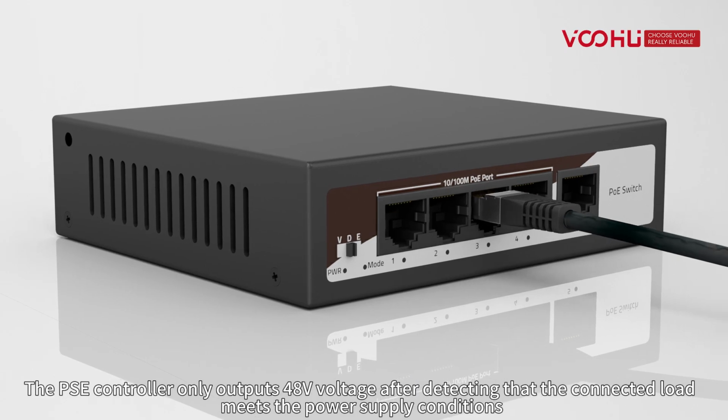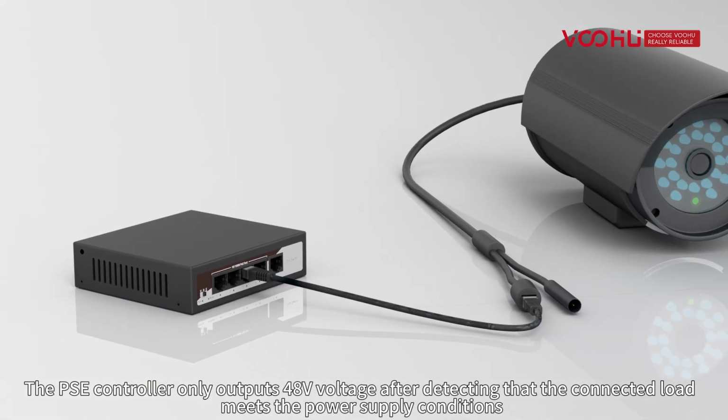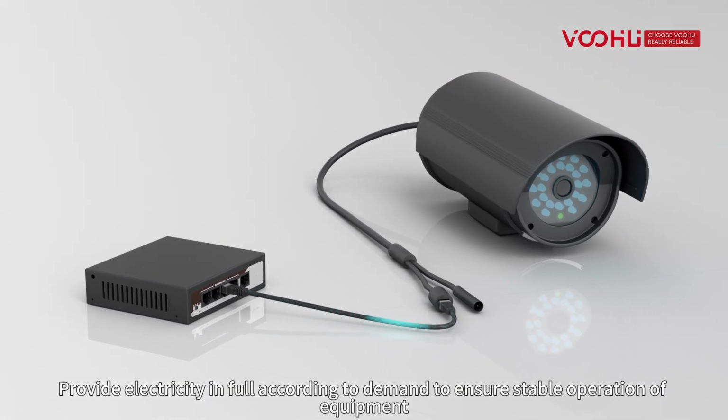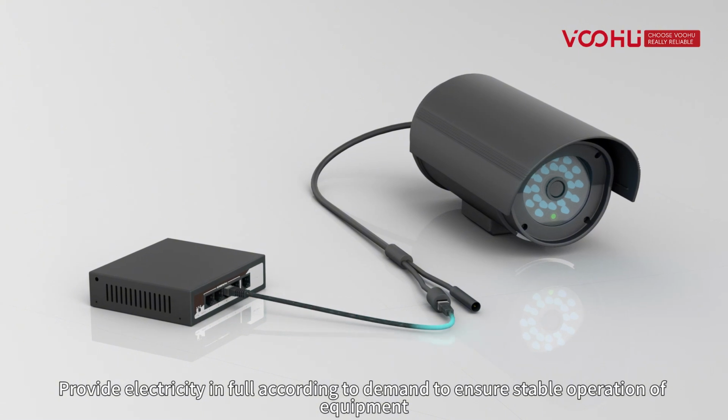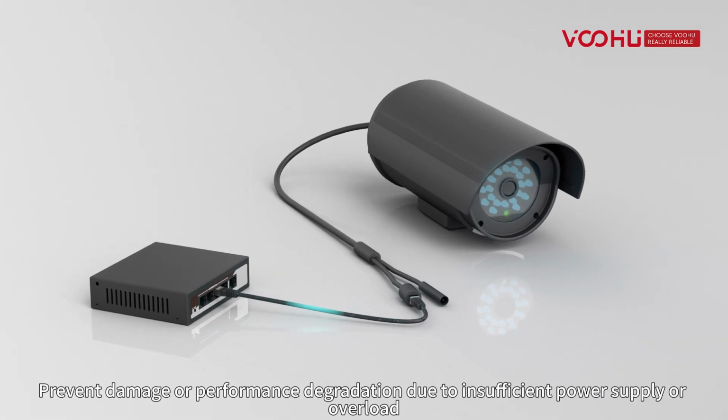The PSE controller only outputs 48 volts after detecting that the connected load meets the power supply conditions. It provides electricity in full according to demand to ensure stable operation of equipment, and prevents damage or performance degradation due to insufficient power supply or overload.